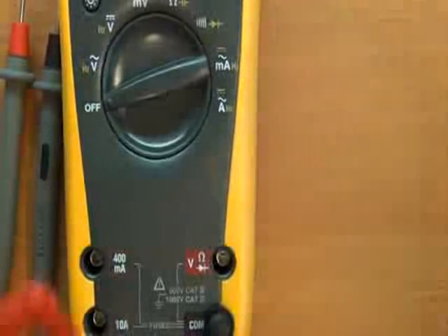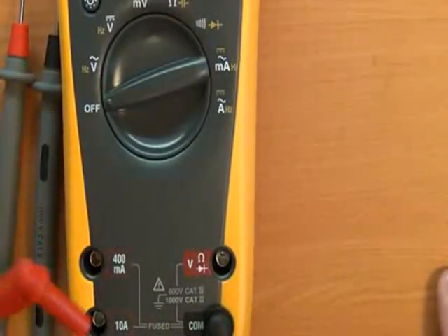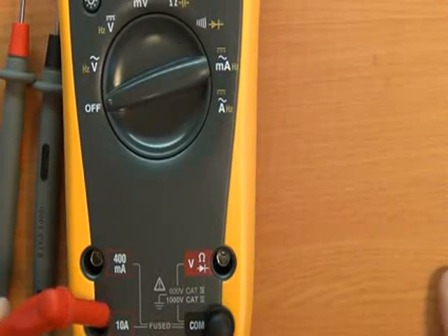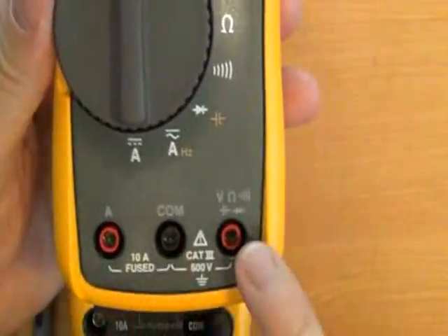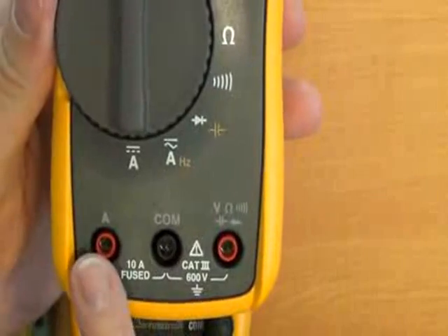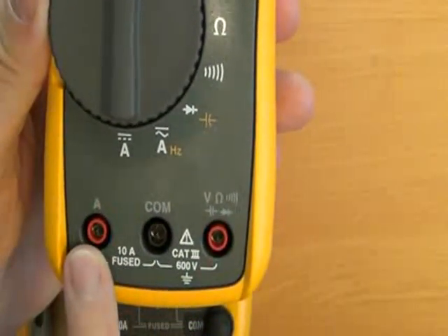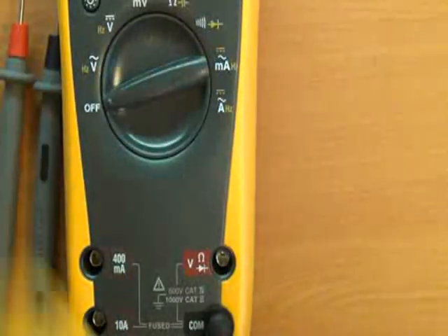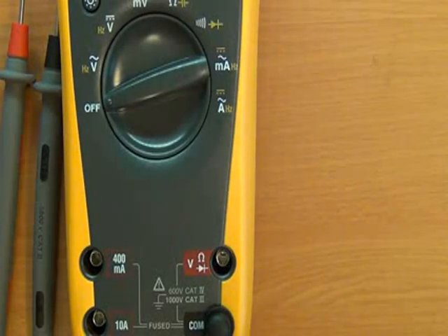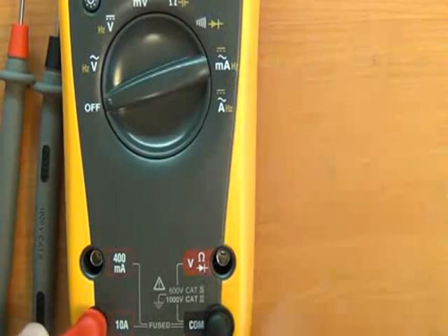It can be as low as 200 milliamps. It could be 500, 600 milliamps. As I showed you earlier, some multimeters just have, and I'll demonstrate it here on this Fluke, some only have 3 connection points, and this is more for electricians. They just have a connecting point to measure amps, higher amp values. You can measure milliamps, but not down to the resolution that you can on, let's say, a multimeter like this. The wisest thing always is to start off in the higher setting down here.